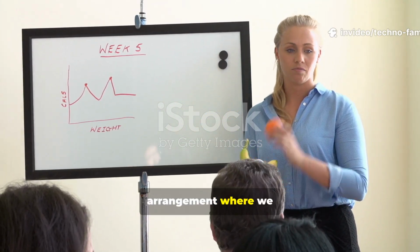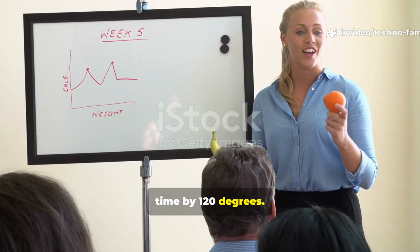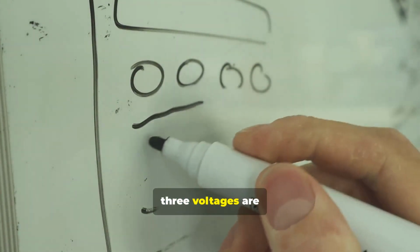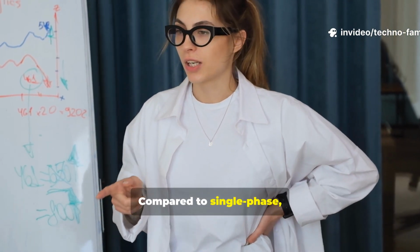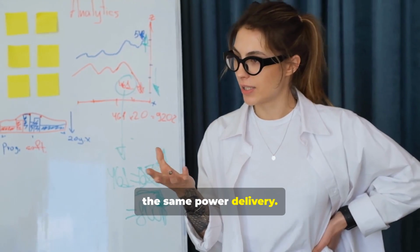It is an arrangement where we have three alternating voltages of the same magnitude and frequency, but displaced in time by 120 degrees. Let's visualize this with a phasor diagram. Notice how the three voltages are equally spaced. This balanced nature is what makes three-phase systems so popular. Compared to single-phase, we get smoother power, higher efficiency, and smaller conductor sizes for the same power delivery.